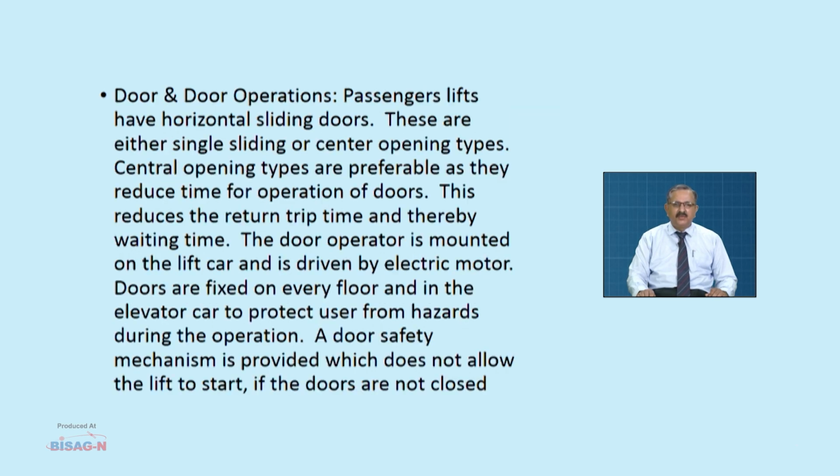Next, door and door operations. Passenger lifts have horizontal sliding doors. These are either single sliding or center opening types. Central opening types are preferable as they reduce time for operation of doors. This reduces the round trip time and thereby waiting time.